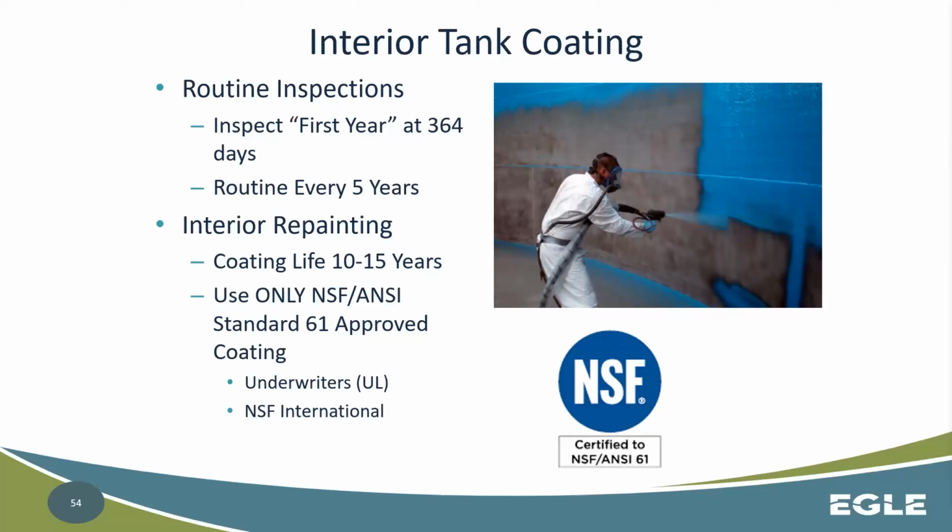Interior repainting. Coating life is typically 10 to 15 years, we say, but obviously that's all dependent on how your tank operates, how your system operates, things like that. Maybe you're having ice formations, maybe it's scraping that up a little bit more or something like that.